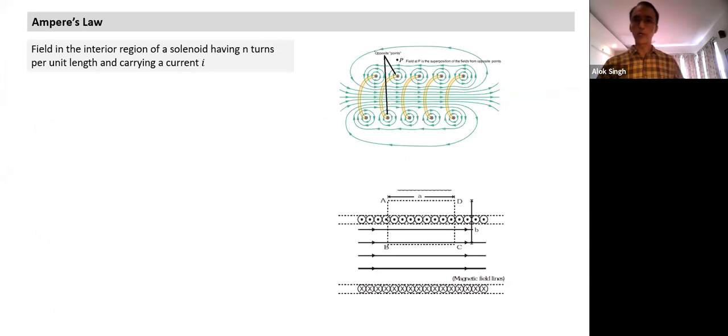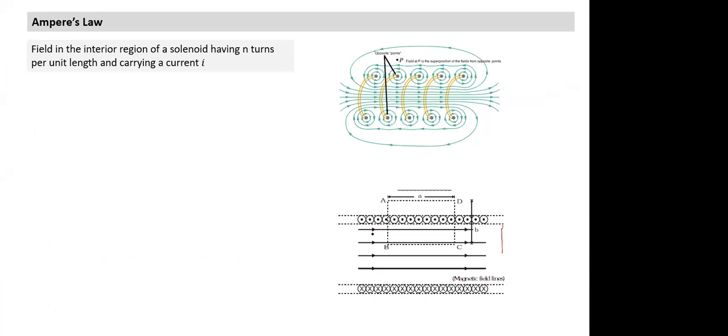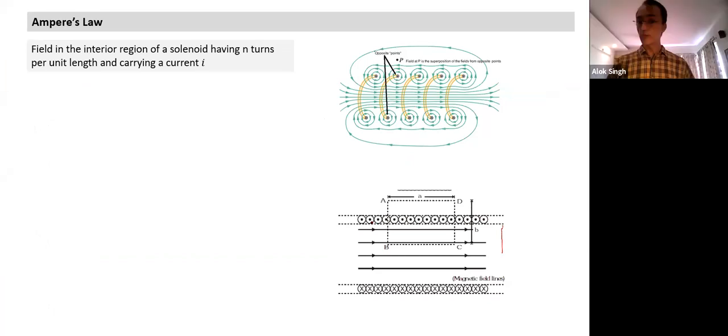When we look at the solenoid, based on the past discussion, this is not easy to infer, but though the radius is blown up like this, we assume the radius to be small. When the radius is small, inside this region the fields will add up, and outside the fields will cancel out. Inside, as the spacing becomes much smaller, as we discussed in the case of the Helmholtz coil, it will tend to become almost uniform.